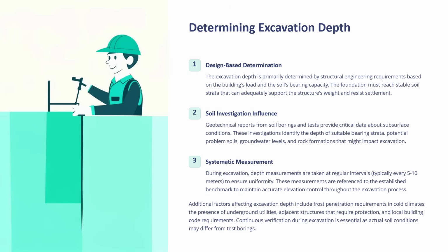So once all these lines have been established, next your aim is to determine the excavation depth. Depth of excavation is very important for any type of construction because it will affect the settlement criteria of the building. If the foundation has not been provided at a proper depth where the soil has the requisite bearing capacity to bear all the load, it will lead to unequal settlement which may affect the building's life and longevity.